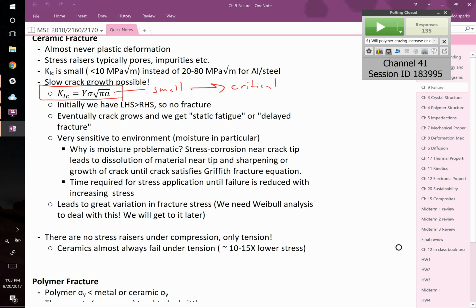What's typically happening is the crack at the tip is growing. If a little bit of water, for example, gets at the tip of the crack, it can dissolve the material at the tip of that crack. Now, normally you don't think of a ceramic as being particularly soluble in water, but when it's a really small radius of curvature, so therefore a high curvature, then your solubility can be much higher. So the very tip of that crack actually can be dissolving, and that makes your crack continue to grow, right? That's one possibility. Because of that, they'll call this stress corrosion cracking sometimes.